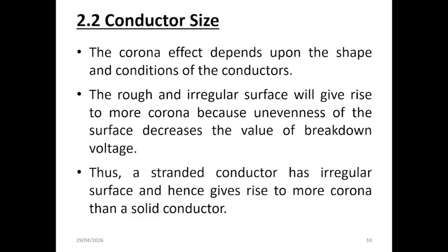Furthermore, standard stranded conductors have inherently uneven surfaces due to their construction, which leads to higher corona losses compared to solid conductors of the same diameter. Therefore, conductor design and surface quality are important factors in minimizing corona effects.